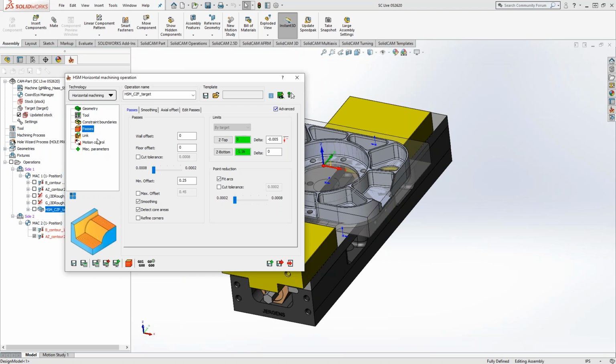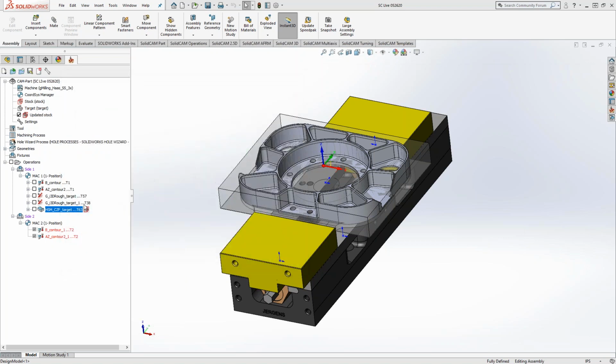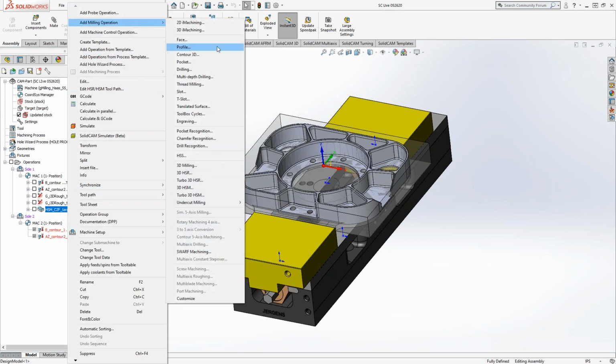For that particular one, what I would do in that case is come back with either a 2D iMachining finishing or a profile operation in there. All those do support tool comp, or we could also do a pocket recognition too, which will support tool comp also. But if we're talking really tight tolerances, I would definitely come back with a profile operation, maybe run a couple passes around. I'm talking tight tolerances, anything smaller than half thou.